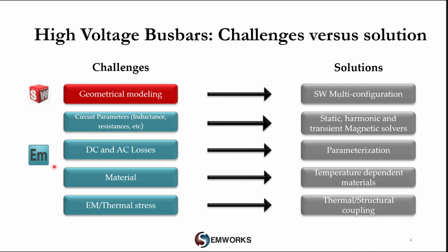Also, electromagnetic losses with magnetic forces can generate structural deformation in the conductors and the metallic housing. These impacts become more important when a short circuit occurs in the busbars. The coupling to thermal and structural solvers is performed within the same study and inside the same environment. No import or export of data, for efficient and accurate results. During our presentation, we are going to see these features and understand their importance in any busbar design process.